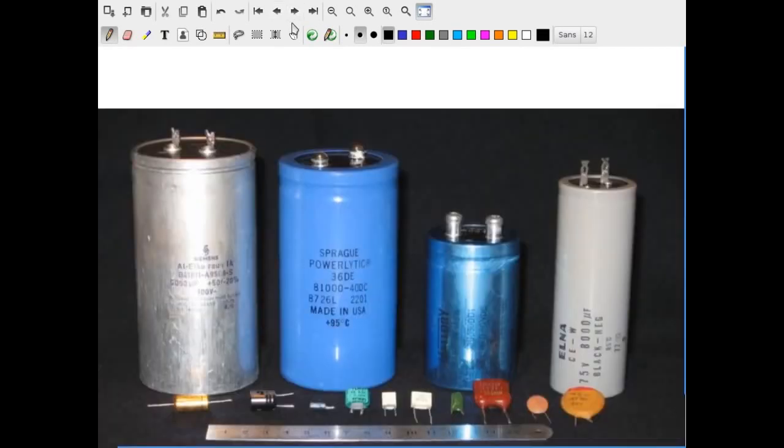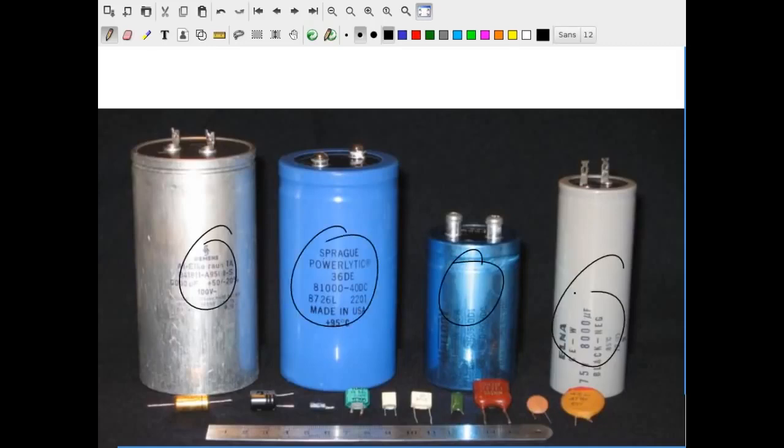Now, of course, human beings make capacitors custom built for different purposes, and this picture just gives you a wide array of such devices. Every one of these is a capacitor, and what you can see if you look at them carefully is in some cases, they'll tell you, for instance, what the capacitance actually is. It's not incredibly obvious that it's written on any of these, but usually you'll see a little number with a capital F after it, and that tells you in farads. There's one of them. So this is about a 5,000 microfarad or 5 millifarad capacitor, and it looks pretty big, but actually you can get capacitors that carry way more charge than this and are smaller than the thing that you see here.